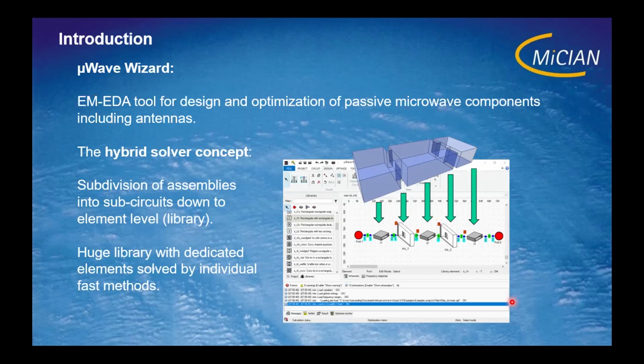In electromagnetic theory, you learn about the modes of a propagating wave. When we design, let's say, a filter, you are working with a propagating signal. In this signal there are propagating modes, and from the input to the output you are matching these propagating modes. This is the mode matching solver.